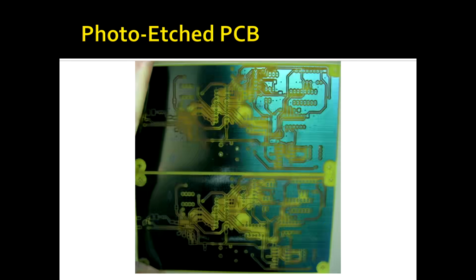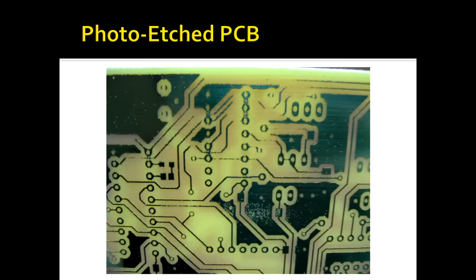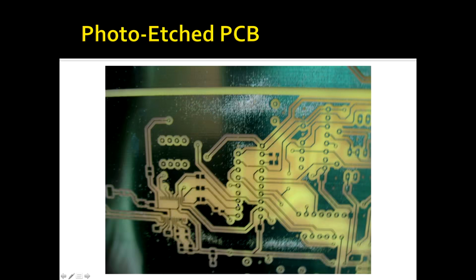So basically I had blurred pads and traces that didn't develop properly. You can see stuff like this probably isn't conducting too much current. Sections right here were wiped out entirely. And you can see the ground plane is starting to get attacked, because you leave it in there to try and eat through some areas, meanwhile it's starting to eat through areas you want to stay there. Here's another example of that.